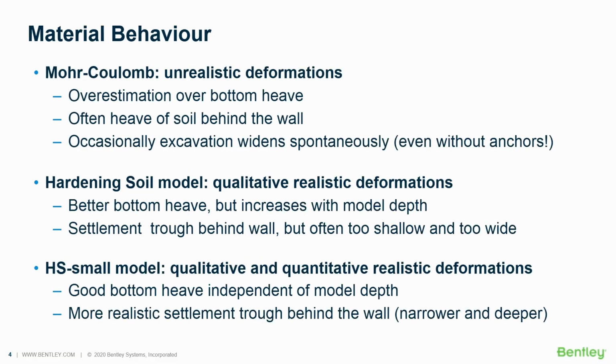The reason why Mohr-Coulomb is not a recommended model is because it provides unrealistic deformations, in the sense that you will observe overestimation of the bottom heave, as well as in many situations heave of soil behind the wall, which is completely unrealistic. And occasionally you could even observe situations where the excavation would widen spontaneously, even without anchors.